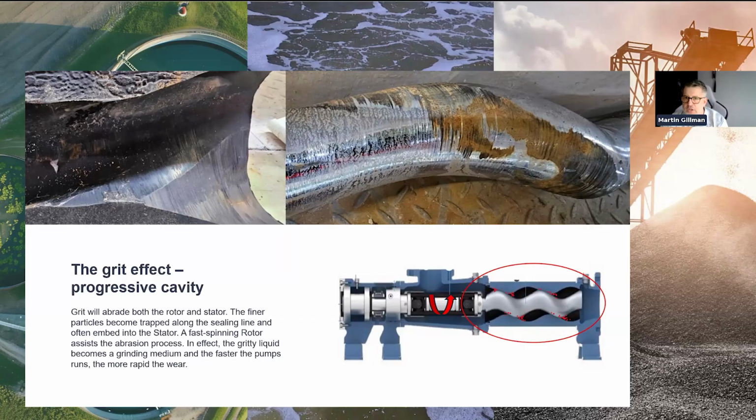And I think if you've not already got there by now, you might be a little bit ahead of me, and that is that if we're picking the right pump for the job, we're going to look to minimize wear wherever possible, so that we don't have this effect or anywhere near this effect quite as rapidly. Then we can push the service life of the equipment out, meaning that we will get longer life from it, and we'll get better whole life costs overall. Because as we'll talk about shortly, whole life costs has a lot to do with the consumption of components in a machine, as much as anything else, like energy and capital.